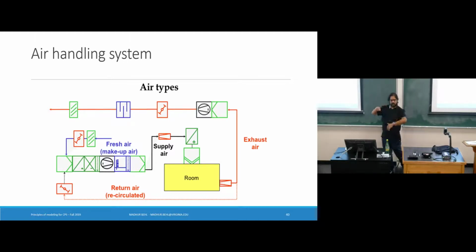The output of that heat exchange is that some air is sent back and sent outside the building, but a part of that return air can also be recirculated. Why do we recirculate air? Because it has been conditioned, right? It takes some energy to condition fresh air. So we can recirculate some amount, but not too much, right? There has to be some fresh air brought in because this recirculated air is high in CO2 and other gases.